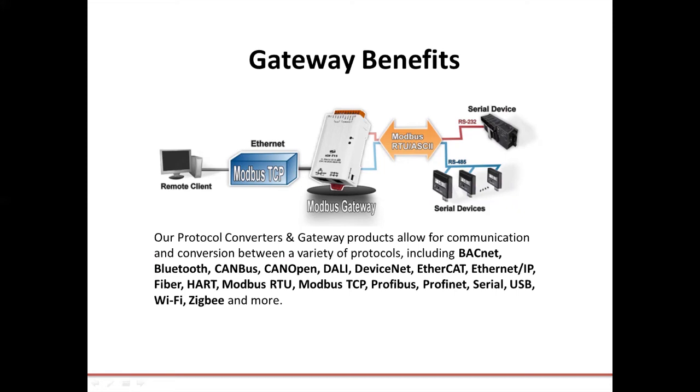For most of our protocols like Ethernet IP, CANopen, and Profibus, the quick start guide and some FAQs help you to bridge the gap. For instance, for our Ethernet IP to Modbus converters, oftentimes customers are more familiar with one protocol, whether it be the Ethernet IP side or the Modbus side. The FAQ section has a step-by-step guide for how to connect using, in this case, RSLogix to a ControlLogix PLC. We have that in our FAQ section, so it makes it very easy to follow the steps shown in the manual.